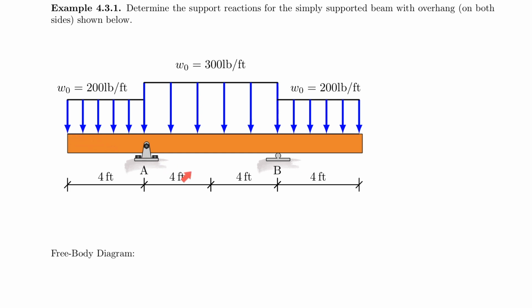One reason for that is because it's a symmetric system. It's symmetric over the center line, and I have two vertical supports that carry the same amount of load on both sides. So one easy way that is not very educational would be to just cut the system here in half and then say everything on this side is carried by RBY and everything on the other side is carried by RAY. And so you could do this real quick. You could say, hey, the sum of the vertical forces that is going down, and then divide that by 2. And that would be your force carried by, for example, RAY, which is also equal to RBY in this case.